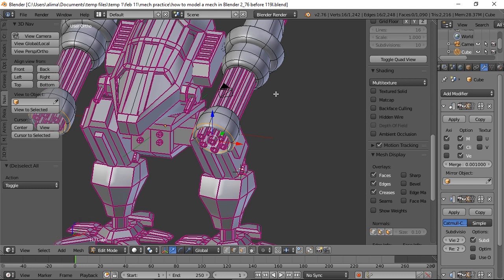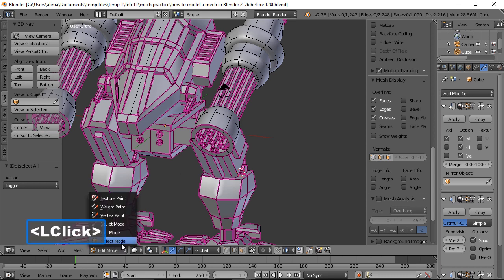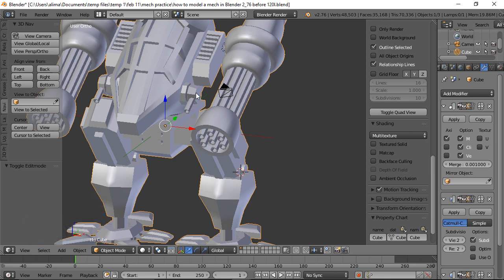And then I'm going to press Shift E and use a shortcut for a mean crease. Then left click to lock in, and I like how that looks a lot better. I'm going to press A to deselect. So right there, we pinpointed hard surface modeling. However, when I click here, then go to object mode, see this? I don't want this to look that hard.